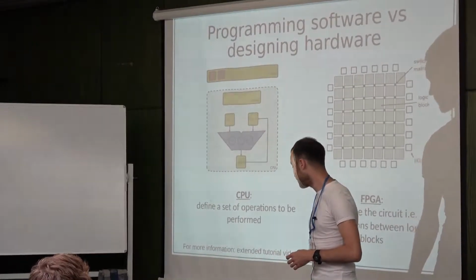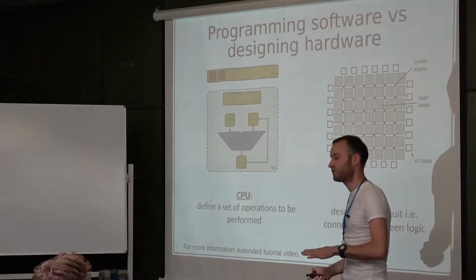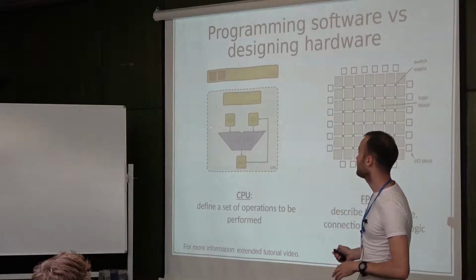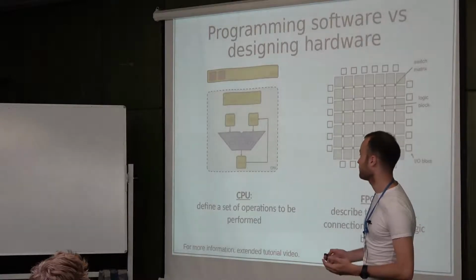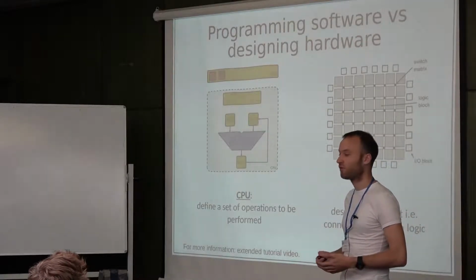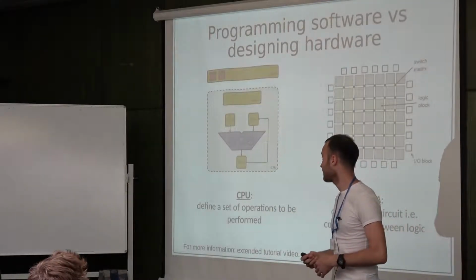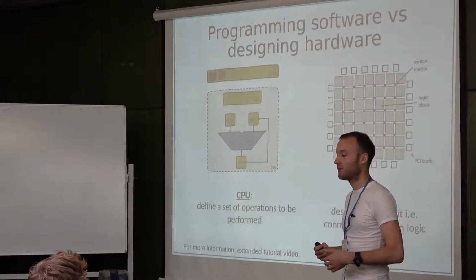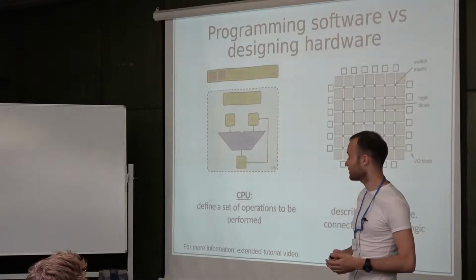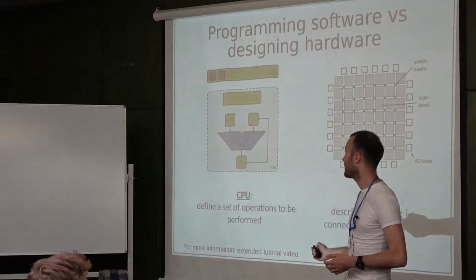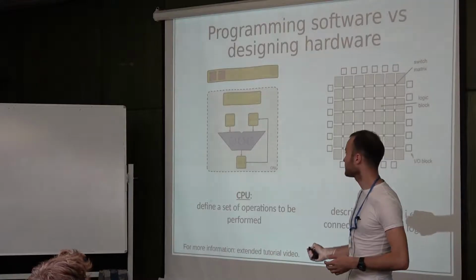If you consider the standard CPU architecture and look with a microscope inside the chip, one of the main components you will see is the arithmetic logic unit. As the name suggests, this is the unit that performs arithmetic and logic operations. This could be simple operations like an AND gate, addition, or maybe some more sophisticated operations like floating point division or square root operation, things like this. So you have an ALU that is connected to registers to store inputs and to a register